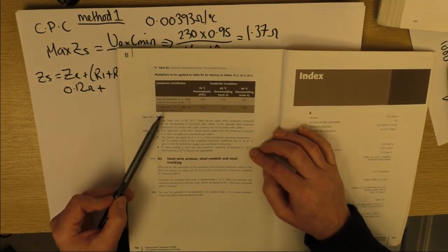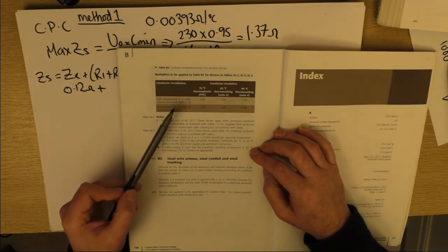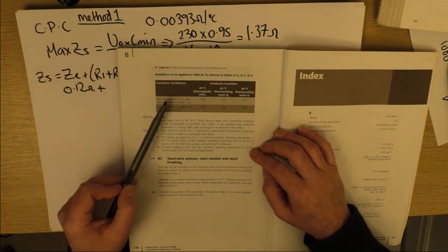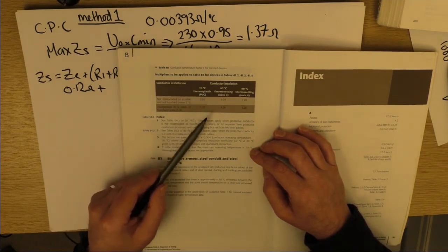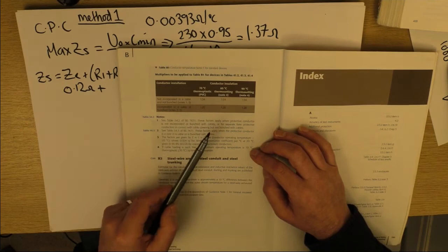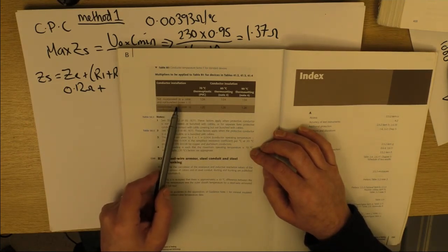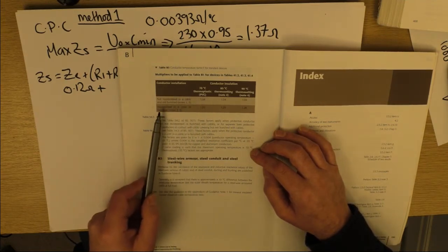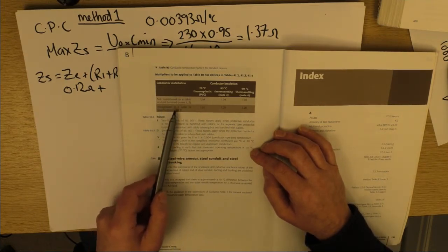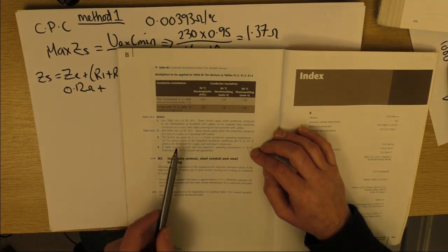So we've got 2 categories here. This is table B3, and in the on-site guide it's I3, I think, but it's the same table. So our cable, we went for 70 degrees C, thermoplastic, singles. We've got "not incorporated in a cable and not bunched", which leads you to wanting to use that one, and then this one, "incorporated in a cable or bunched". Then we've got some notes here, so notes 1 and 3.